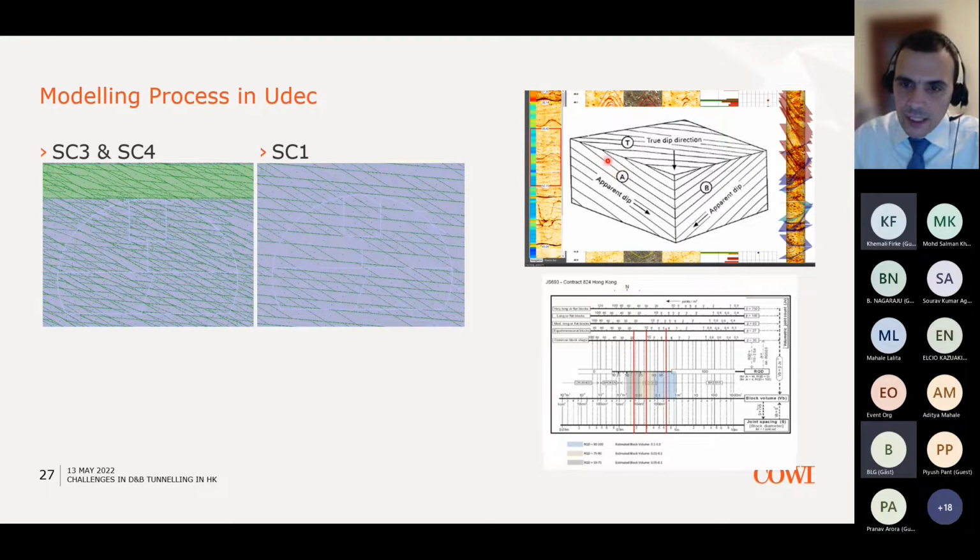And the way to see that is that if you take a slice of this along this plane, that would indicate that the sliding plane is in this direction. Whereas if you take a section along this side, the sliding plane would be along this direction. And then the reality is, if that's the joint network, that the blocks will slide differently in different directions. So you need to make an assessment of how best to model the wedges in a 2D analysis.